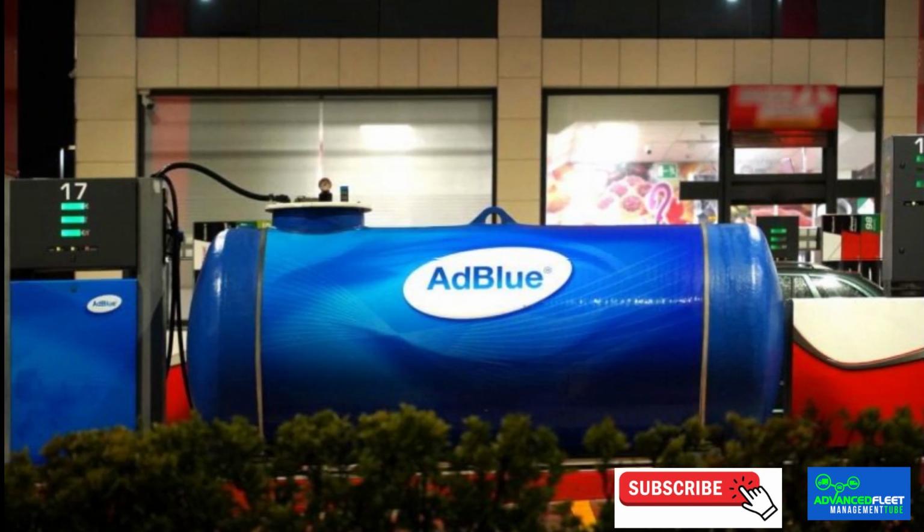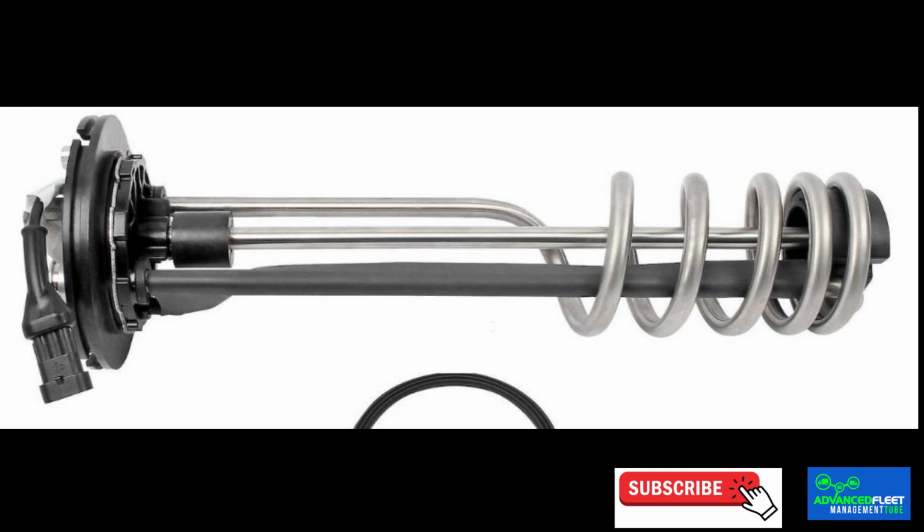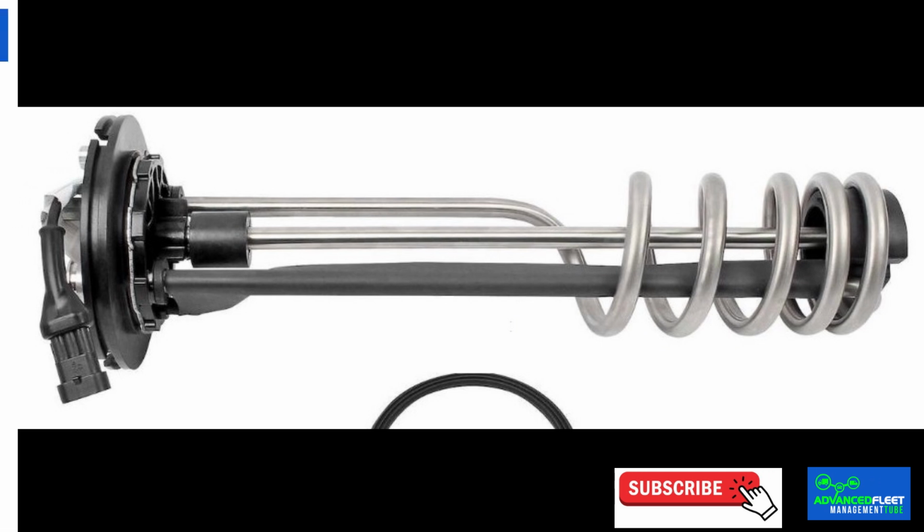Proper storage. Adblue should be stored in a cool, dry place, away from heat sources and direct sunlight, to prevent product degradation. During winter months, it is particularly important to protect Adblue from low temperatures to avoid crystallization. Checking the sensors. It is important to regularly check and calibrate the Adblue system sensors to ensure that they provide accurate readings, thus avoiding incorrect dosing that can affect vehicle performance and increase emissions.